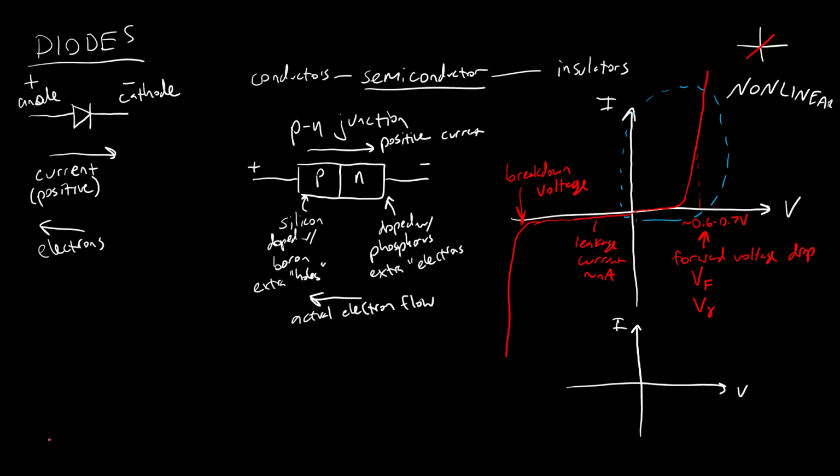One where we just have zero current, so at any voltage less than the threshold voltage, including a reverse bias or negative voltage, we just have zero current. Then we treat it as a constant voltage drop, or constant forward voltage, once you reach that threshold, but you can't have a higher voltage drop than that. No matter how much you try to increase the voltage, the diode is just going to keep conducting more current, but it's going to be at a constant voltage drop, and we'll go over some examples of what that means a little later in this video.